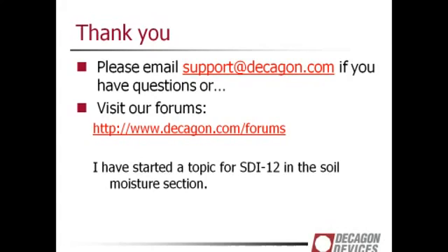So it looks like we're getting to most people's questions. Oh, here's another interesting one. Could you have more than one type of SDI-12 sensor on the same port? Yes, you can actually. I've done this. It works. The main issue you need to consider here is data storage. So say one sensor I've used sends back three readings. Another sensor I used sent back 5 readings. They were both on the same port, as they had different SDI-12 sensors.